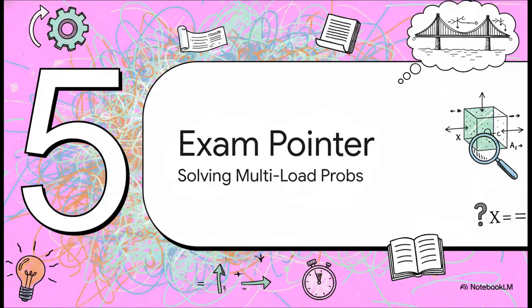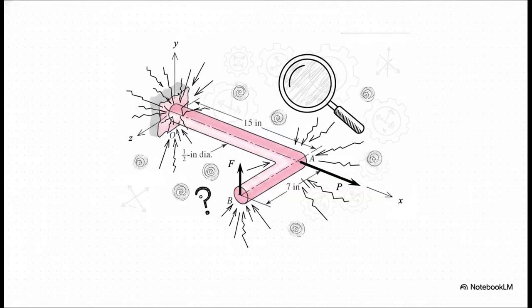All right, let's wrap things up with Section 5. Exam pointer. Solving problems. Let's put this into practice. Picture a classic exam scenario. You have a cantilevered bar dealing with combined loading. Let's say there's a force P acting axially at one end and a transverse force F pushing upwards. This multi-load setup is the ultimate investigative case study. Your professor wants to know, is this bar going to break? And if so, exactly where?